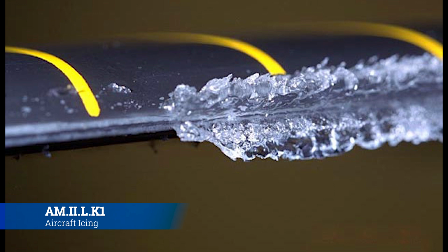And what you'll see is that as you're flying, all of a sudden your RPM starts to go down, because the heavier and the more disrupted that flow is of that prop going through the air, the more the engine has to work, and the engine is already kind of maxed out at a certain fuel setting. You'll see the RPM start to dip down, dip down, dip down, and that's one of the indications that you'll know that you have propeller icing.